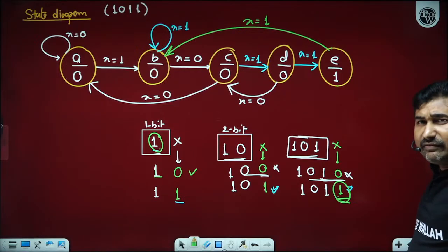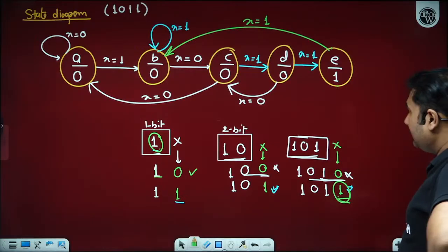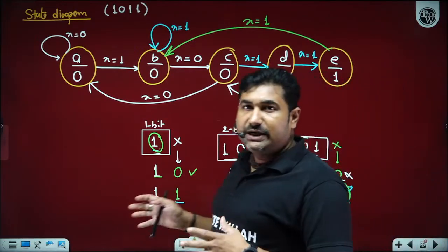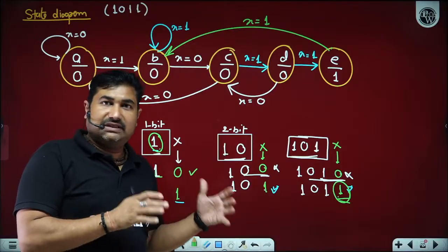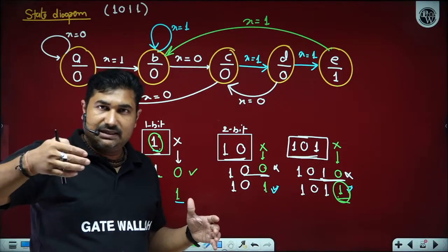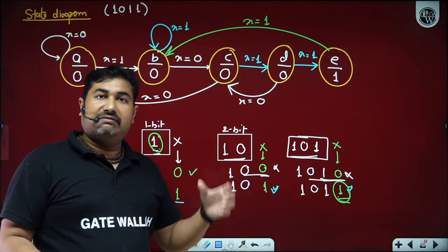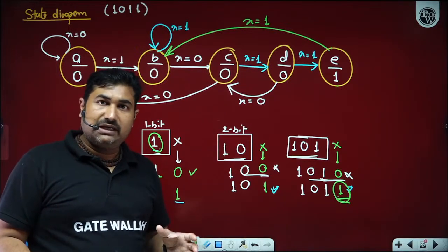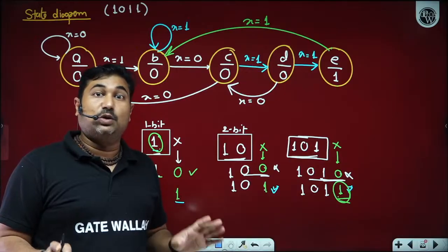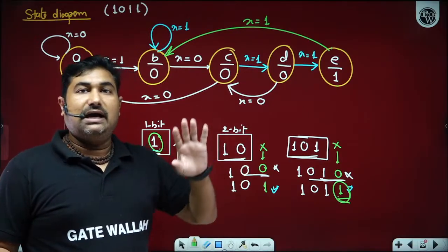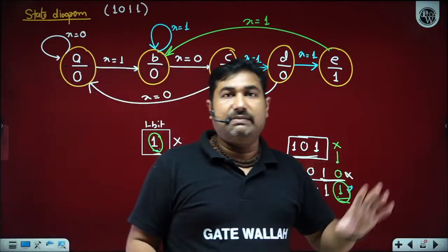The same way can be utilized to design with the Moore model as well. In the Moore model, what do we have to do? First, we need to draw the state diagram. After the state diagram, we have input x, which may be 0 or 1, and we have states. Available states are from 0 to 4 only. The rest of the states will be treated as don't care, and the outputs for them are treated as don't care in the K-map. Is it okay?